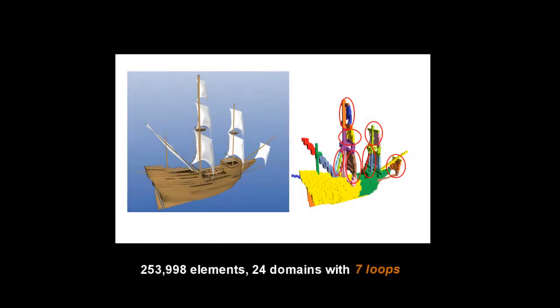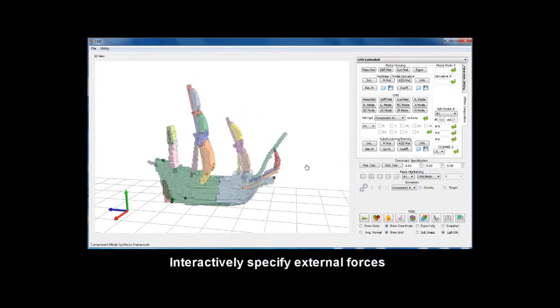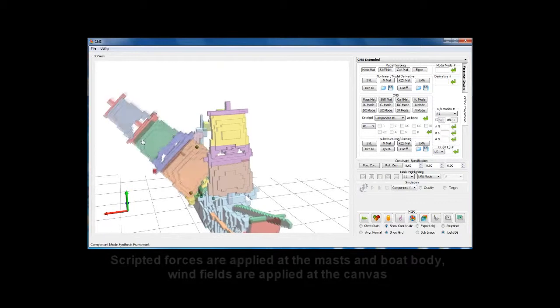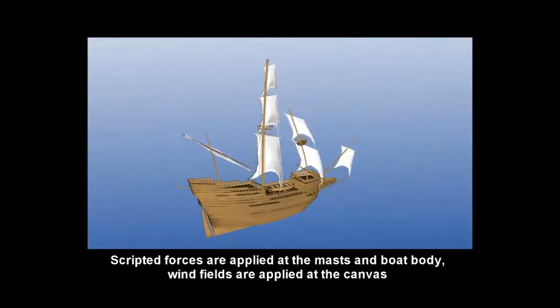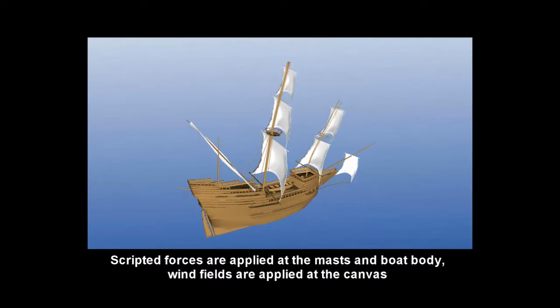Finally, we show a seaboat model with over 250,000 elements with 7 domains. It can also be interactively manipulated by the user. We applied scripted force at the mast and wind field at the canvas. We assign highly stiff material to the mast and soft material to the canvas, while higher order inertia modes are also assigned to the canvas for enriched local deformation. Interesting results can be simulated.